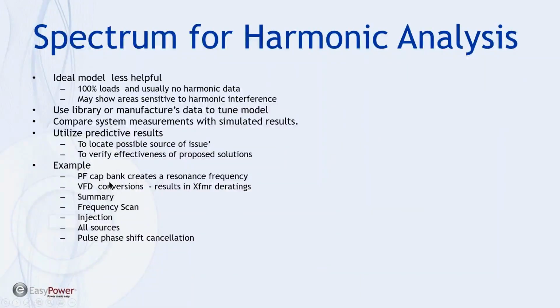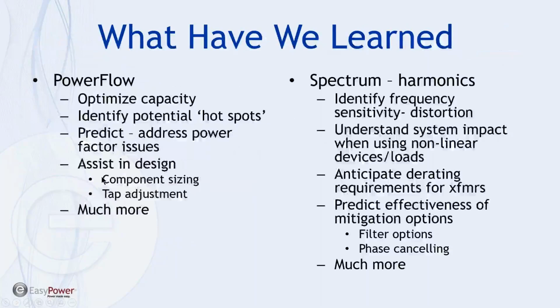So what we've shown is basically the ability to use PowerFlow to optimize the capacity of our system, identify potential hotspots, deal with power factor issues if we have large inductive loads, also assist in design for component sizing and tap adjustment, and then more based upon whether we're in the new design phase or doing addition to the existing system.